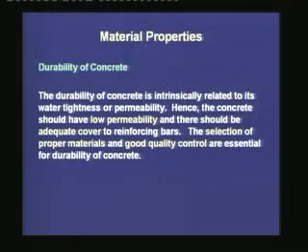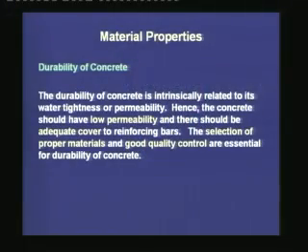Now, the durability of concrete is intrinsically related to its water tightness or permeability. See, there is a difference between permeability and porosity. Permeability means that when there are connected water paths within the concrete, then water can ingress into the concrete and cause durability problems. That is why, in order to enhance the durability of concrete, we need water tightness or low permeability.